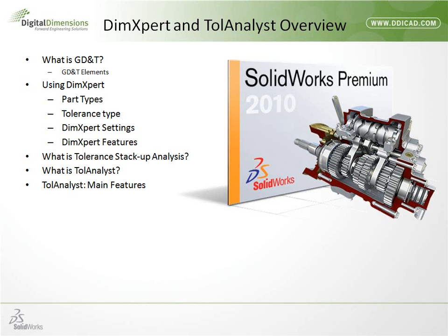I'll introduce you to the DimXpert, and when using the DimXpert, we take a look at the different part types that we can set up, the different tolerance types that are available. We'll talk about the DimXpert settings and then the features that the DimXpert supports. Then I'll talk about what tolerance stackup analysis is. I will introduce you to the TolAnalyst, and then we'll talk about the main features of the TolAnalyst. And of course, we'll be demonstrating this as well.